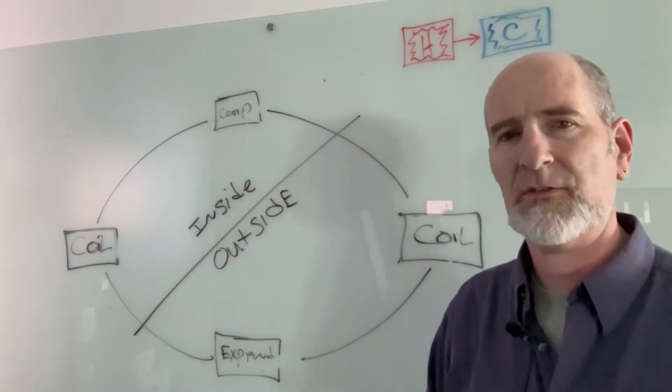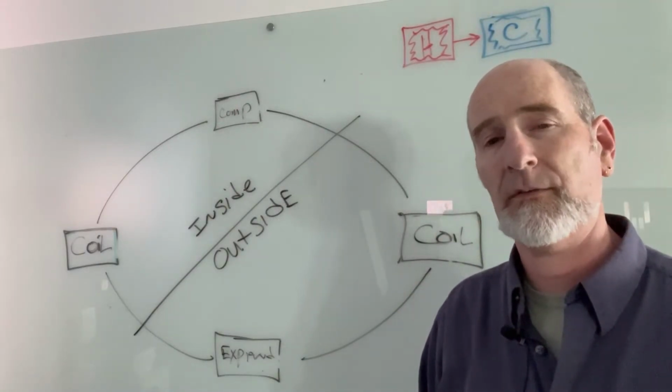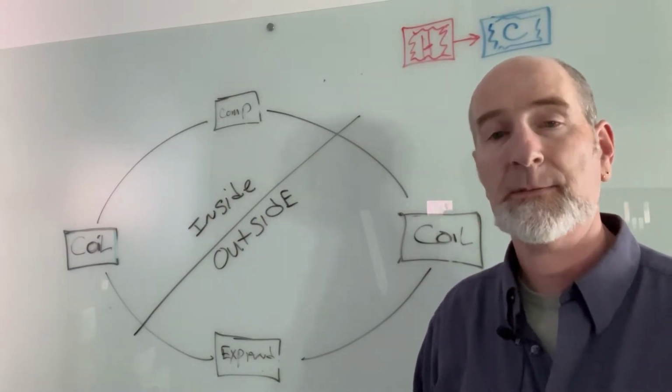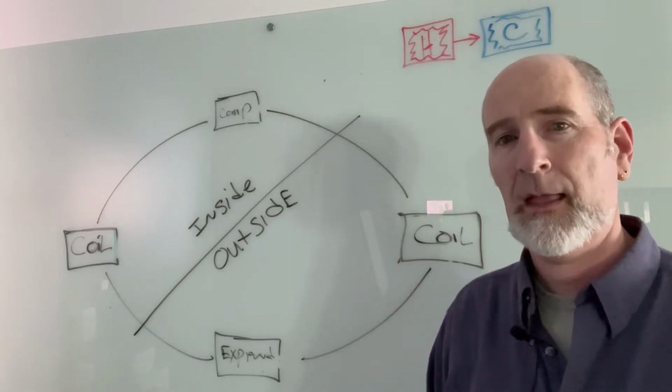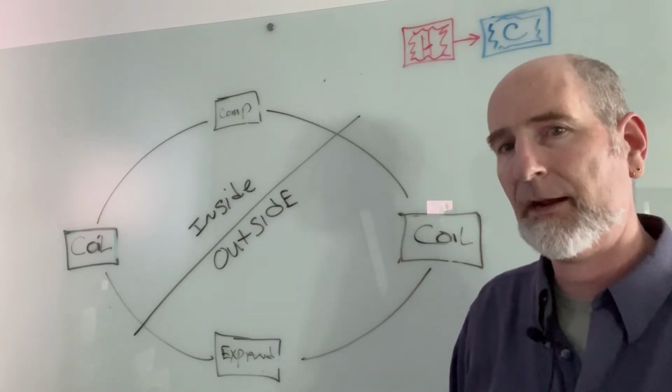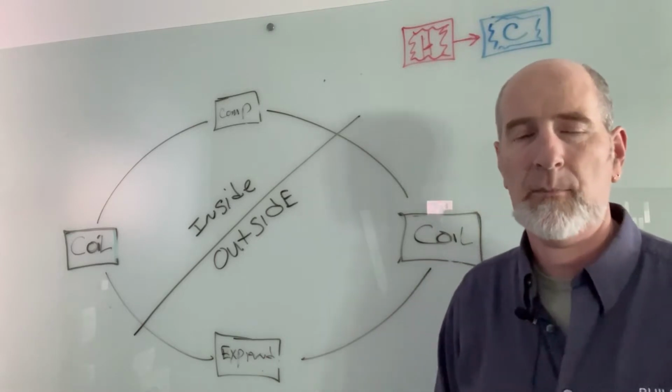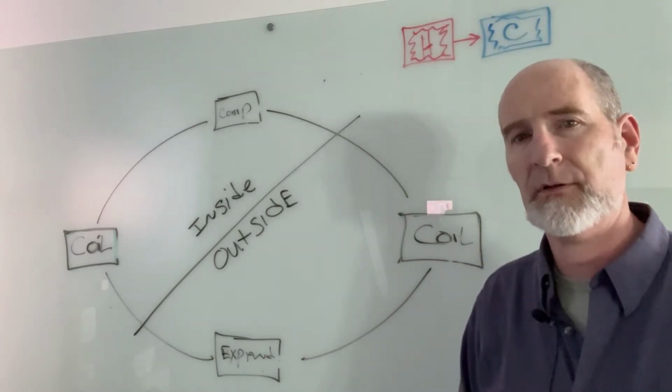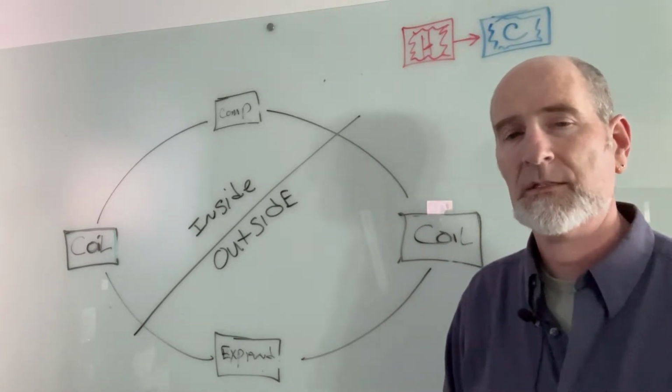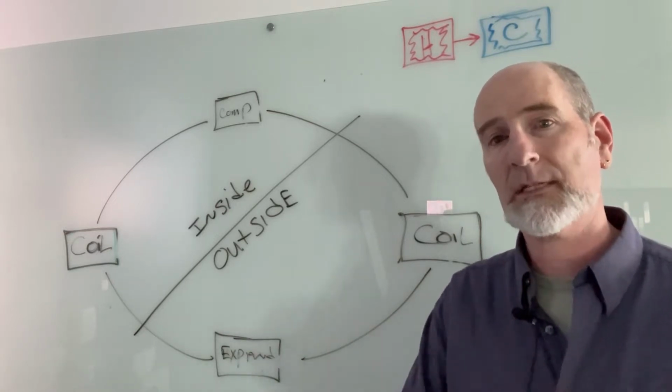Hi, I'm Robbie Schwartz with Built Tank Inc. And today we're going to talk about the refrigeration cycle, specifically with regards to heat pumps and air conditioners. Basically, an air conditioner is a heat pump, but a heat pump has the ability to reverse the cycle, so it can take energy from outside to inside.